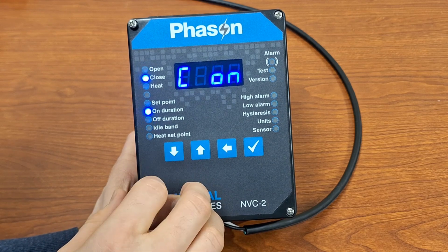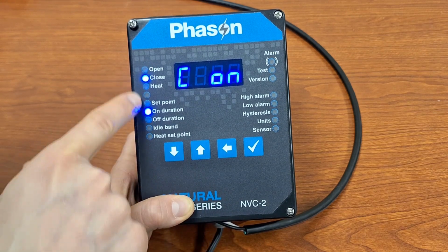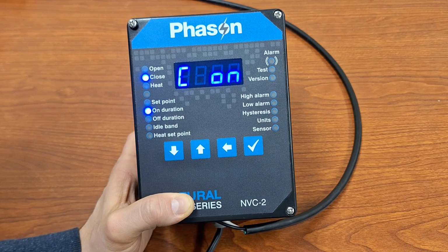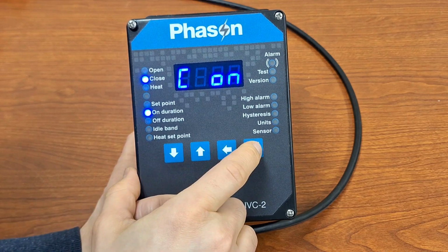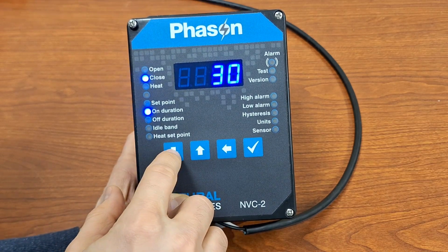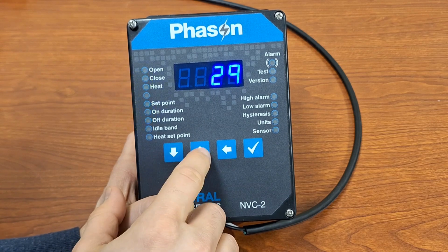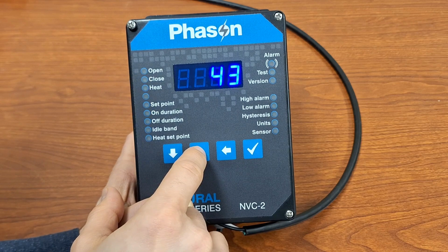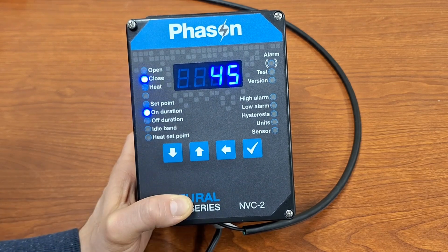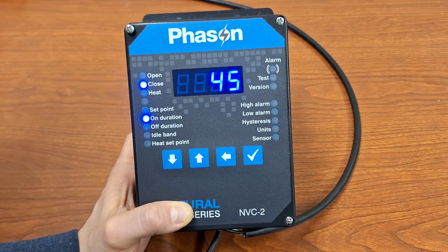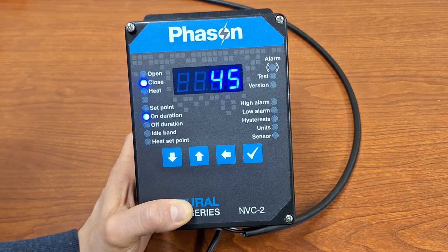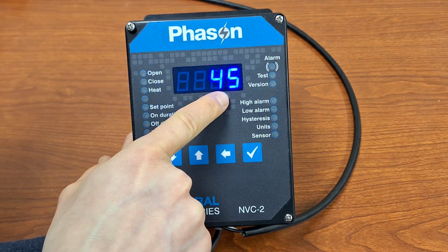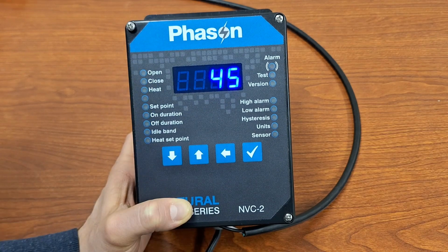And then the next thing, now we've got close on duration. So you can set it up differently. Let's say our on duration for close, I actually want them to be more aggressive in closing because we want to make sure that things aren't getting too cold. If you're in a greenhouse, you don't want your plants freezing. So I'm going to be a bit more aggressive. I'm going to close for 45 seconds. So if it's getting too cold, I'll close for a full 45 seconds,